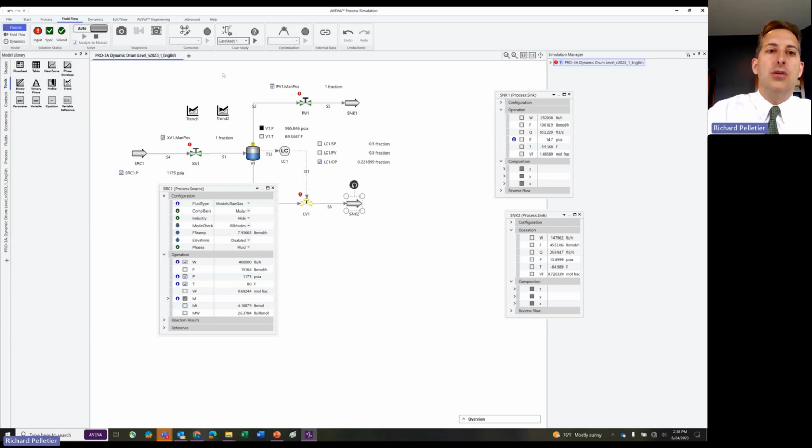Typically, what you do is you'll use these scenarios in occasionally some of the steady state modes like process mode or fluid flow mode to set up what's going to end up being run in dynamics. And the real benefit of scenarios tends to be in the ability to run dynamics for specific lengths of time or until certain conditions are met, and then make changes and then continue running and cycle through these things while automating this sort of dynamic run behavior.